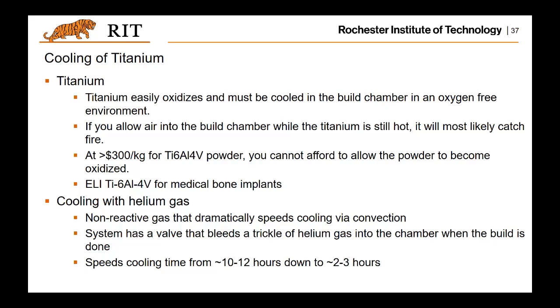Usually it takes 10 to 12 hours if you do not have helium gas filled. But with helium gas filled, the cooling time could be reduced to 2 to 3 hours. So that will speed up the cooling process dramatically.